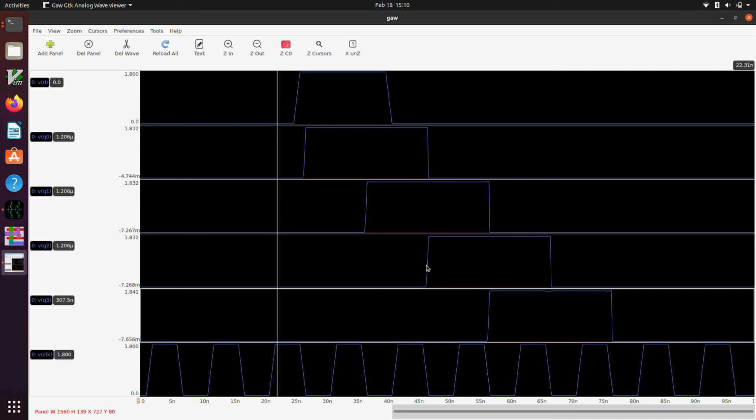We could also take our negative D flip-flop, and by rearranging the geometry so that the other latch comes before, like we exchange the phi and the phi bar latches in their order, we would create a leading edge triggered flip-flop. And of course, we could go through that exercise, but it would be very similar to this whole thing, so we're not going to bother doing that.